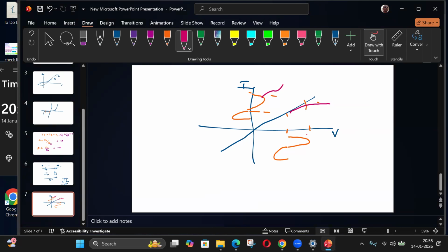I can also make this variation at this point and get the corresponding output here. For a resistance, it does not matter because wherever I put, I get a decent curve. But if the thing is not a straight line, it's a curve, I have to choose a proper region where it's approximately a straight line, for a nice output. So it's important to choose an appropriate point for this. This choosing of the point is called biasing.